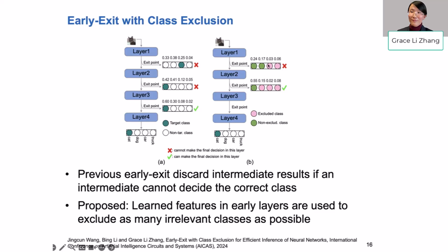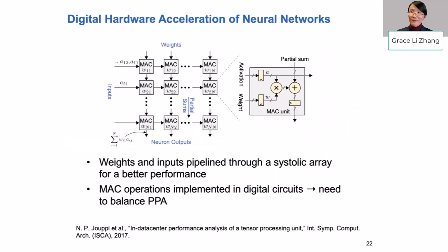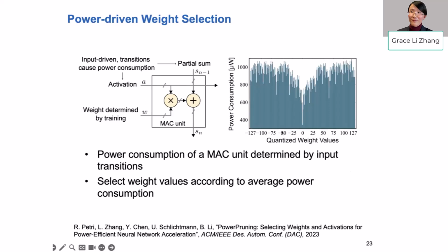When you report the power consumption per weight, on slide 23, where does the data come from? I guess that's from simulation, right? Yes. For example, we first use ModelSim to extract the signal switches in the MAC unit when we enumerate those activation and partial sum transitions. And then we use Synopsys PrimePower. I forgot the name of the tool. It can evaluate the dynamic power consumption according to the signal switches. We use some tools to extract them.